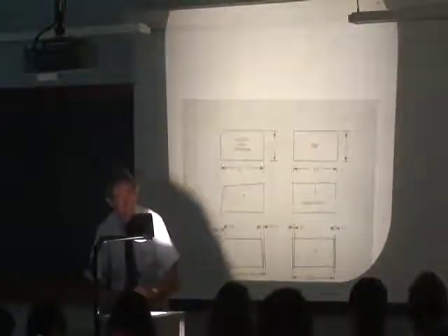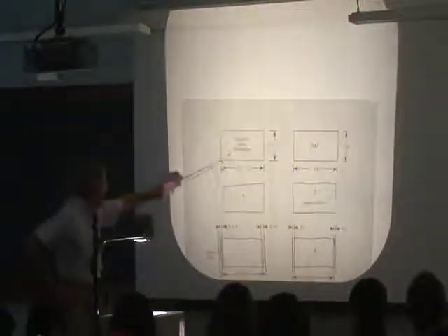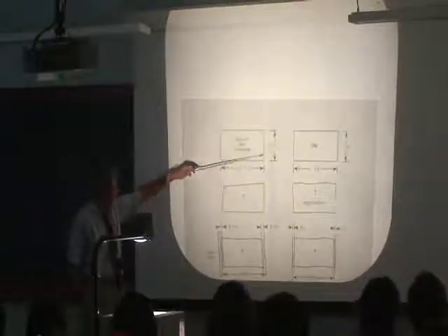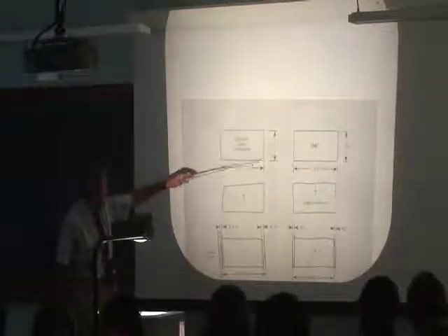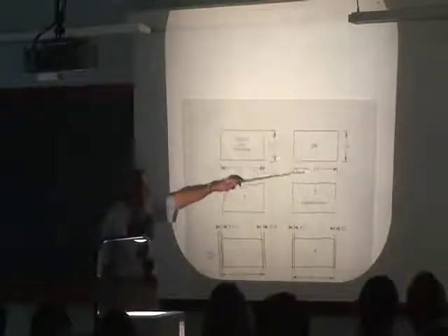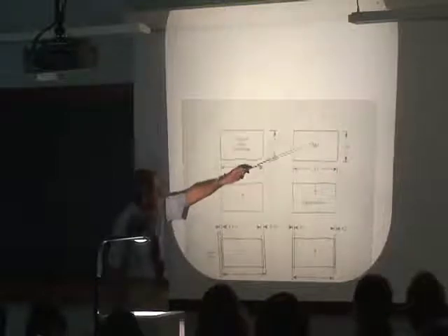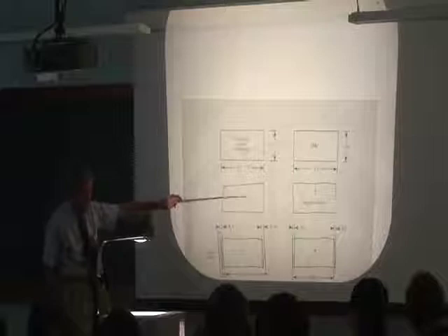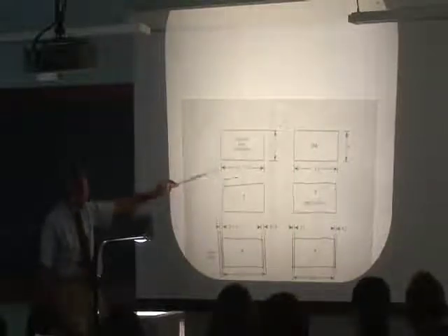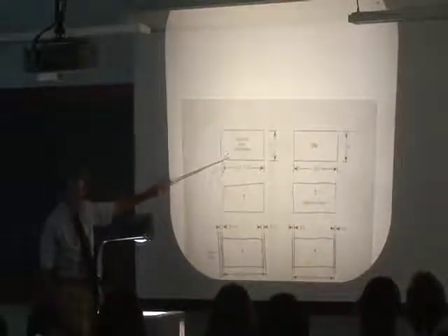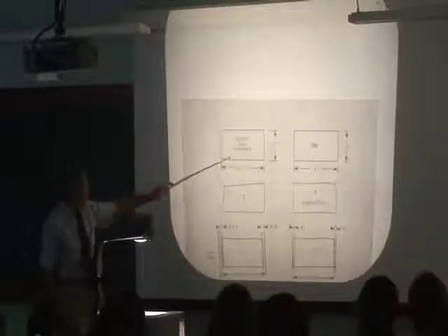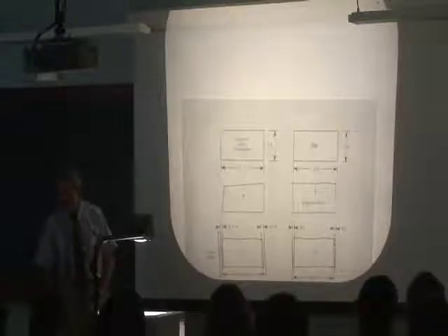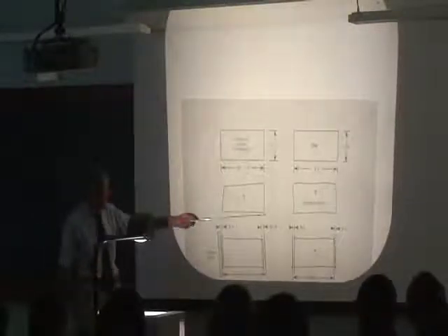Okay, well, here's a very simple drawing. Length and height, plus and minus 1 in each dimension. If you produce this part, which is 5.9 by 305, you could say that's okay. Now if you produce this part, it's a little bit unclear, because this doesn't tell you what the angles are supposed to be. And they clearly cannot be exactly 90 degrees. How much off can they be? It doesn't say. This is tougher.